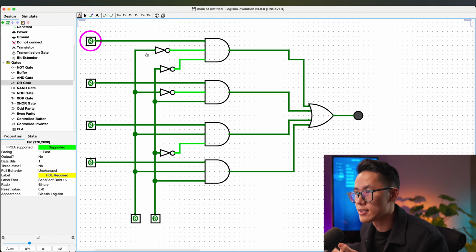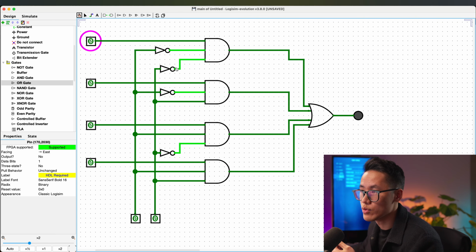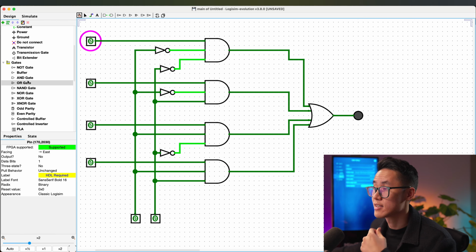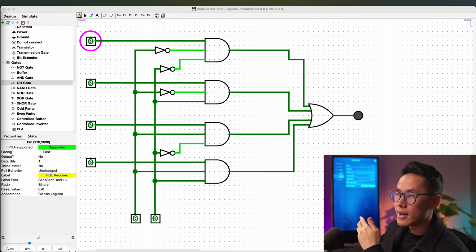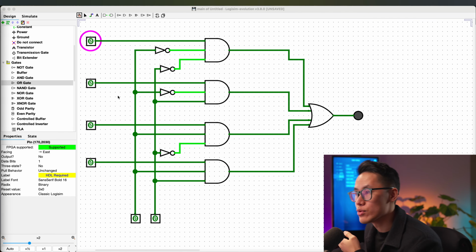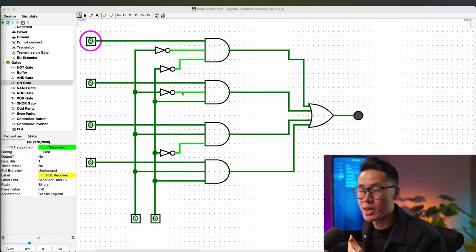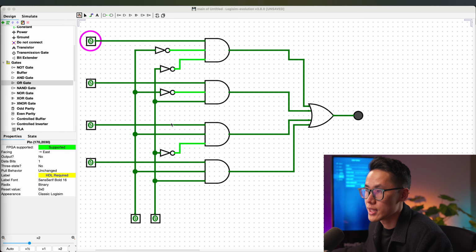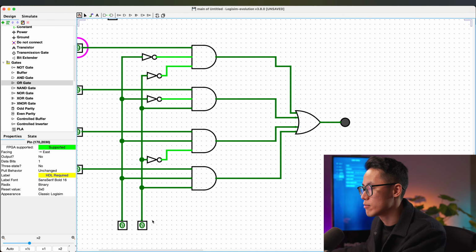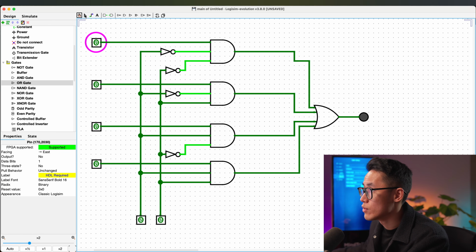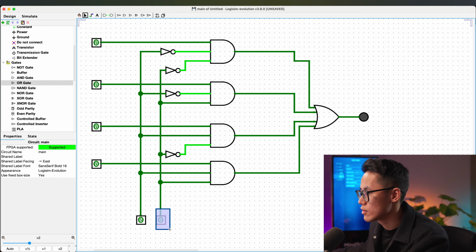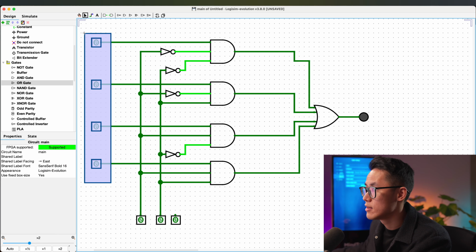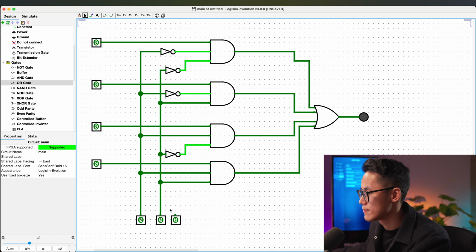Yep. That is a 4-to-1 mux if you do it by yourself, just using the fundamental gates instead of the components. Now in the lab exercise, you will do this for an 8-to-1 mux, but I hope you can get the ideas and do it. If you want to make it an 8-to-1 mux, you will want to create another pin, and then you create 4 other inputs.